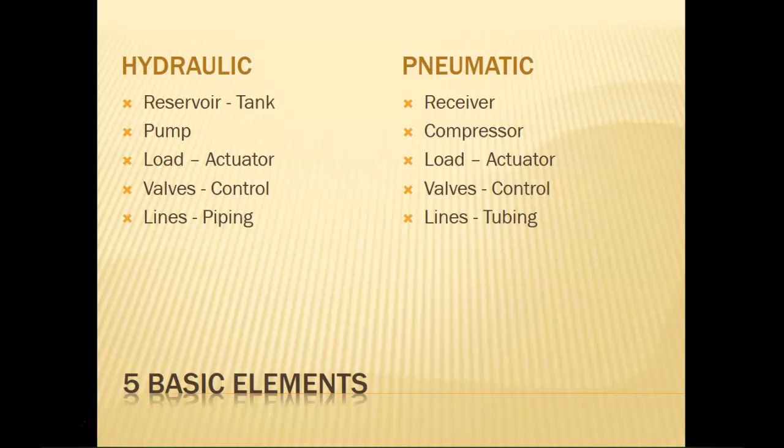You have to have a compressor, however, because if you don't have something to compress air, it kind of becomes useless. You can't really do much with it unless you compress it. Again, you have to have some form of a load in the form of an actuator. You have to have something that does some form of work and uses the compressed power to do something. Otherwise, again, what's the point? You have to have, again, the valves to create control so you can turn things on and off. You can move it left and right, however you need to do. And then you have tubing. Now, this one generally is a lot of tubing.